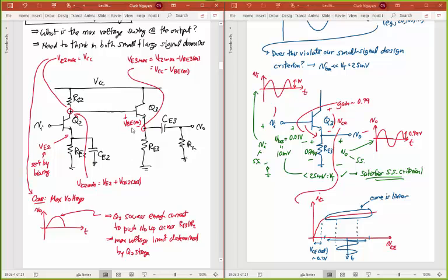And we're talking about the total voltage drop across that, not just the small signal voltage drop there. So that's why we're thinking both in terms of small and large signal domains now to determine how much voltage excursion you can get at the output there. And so hopefully you can see that because this node here is limited to VCC, the maximum voltage you can get on this node here has got to be that VCC minus VBE, because you have to drop that VBE across the base to emitter junctions on this Q3 transistor.